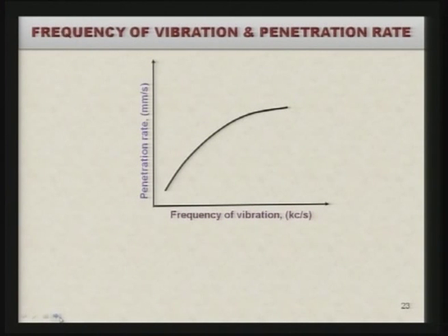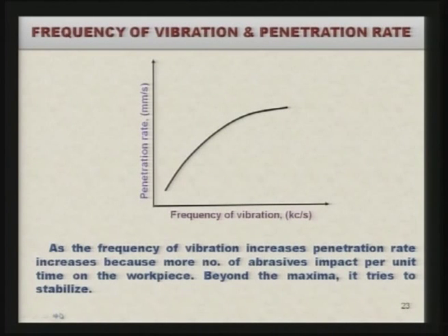The relationship between frequency of vibration and penetration rate is shown over here. As we can see, as the frequency of vibration is increasing, the penetration rate is also increasing, but it also stabilizes. As the frequency of vibration increases, the penetration rate increases, because a larger number of abrasives impact per unit time on the workpiece, and definitely the penetration rate will increase. Beyond the maxima, it tries to stabilize, as we can see over here.